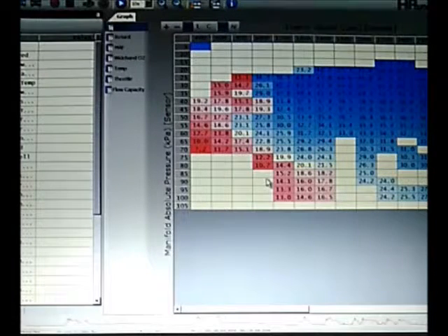But this is focusing very specifically on making your core table changes, like your fuel map and your spark table to some extent as well. This is like the real tuning part that takes a lot of time and iteration and all of that. The other stuff is more like binary. You flip it on or off, and it's set forever. But this is the stuff that you need to master if you want to be a good tuner and if you want to get your car in tip-top shape and keep it that way.